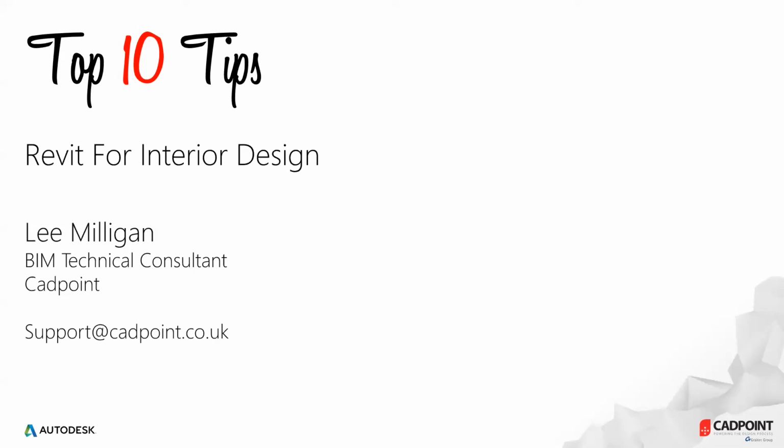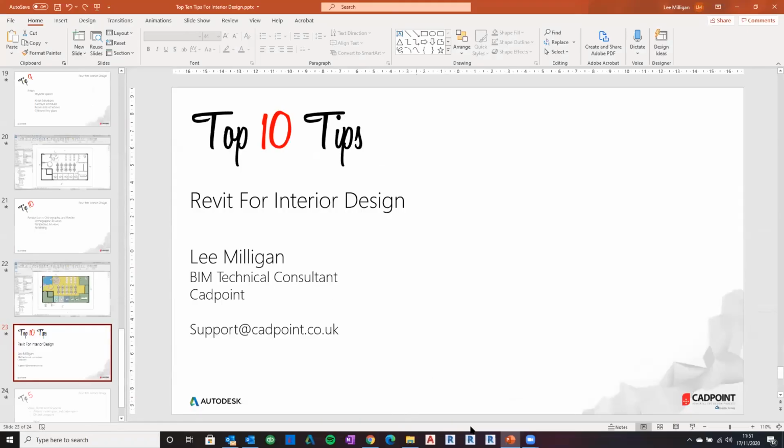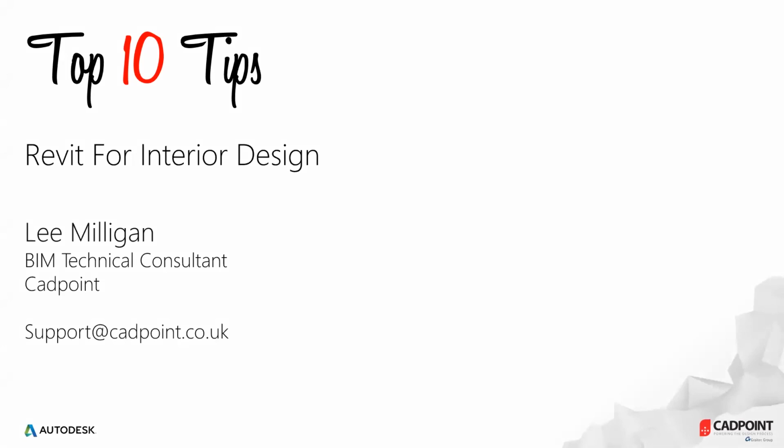We've got a question from Amos. Is there a walkthrough of the model? Are you cutting walls, etc.? I think there is through Revit, isn't there? Yes, you can do a walkthrough. It's done on a path basis though. So you sketch your path, you tell it at particular keyframes where you're looking, and you can then go in and do a video animation around that.